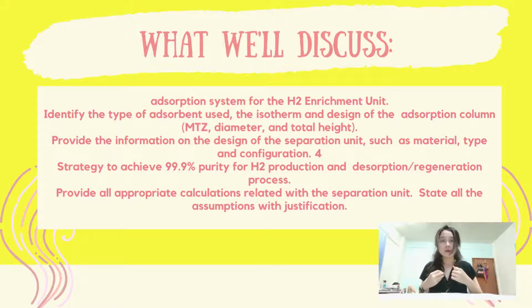Next, I would like to brief you on the selection for the hydrogen enrichment unit. The hydrogen enrichment unit that we are going to select will be the pressure swing adsorption, which is known as the PSA technology. The reason that we choose the PSA is because we can extract the hydrogen from the synthetic gas under high pressure.